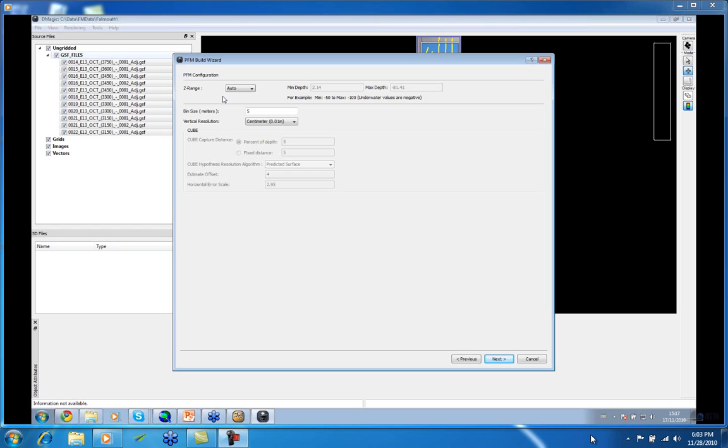One of the things that you have to be careful of is if you do leave it on auto, the data can actually go into the PFM, but then be rejected because it's outside of the Z range. This is an important issue, because if it's rejected on the way into the PFM and you go and clean all the data in your PFM, which you think is correct, and then you unload it all back, those points which are outside that range won't have been even touched by the PFM.